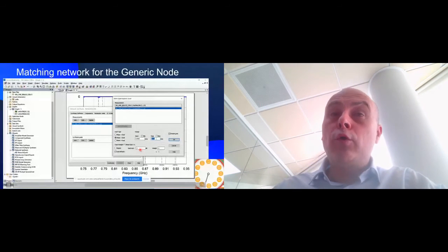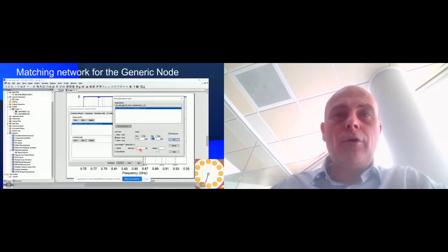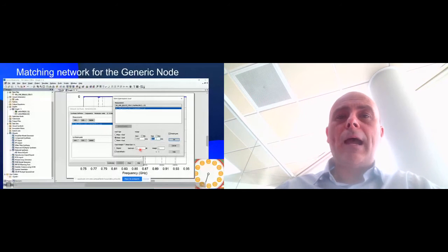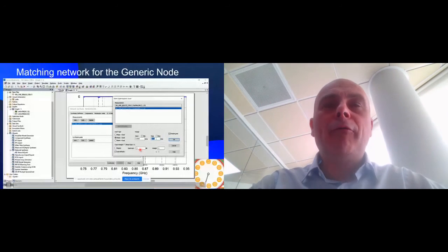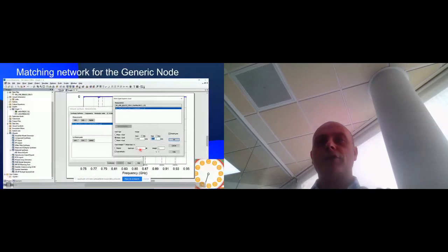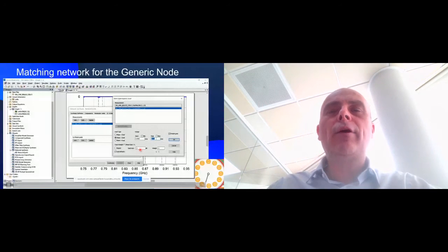In this case, it's only 2 components, and it gives you 2 possibilities. One topology here, another topology, a combination of 2 inductors, for instance. Let's pick up this solution. So we have the antenna booster, and we have the antenna booster with a matching network, and this will represent the transceiver. This port here is the transceiver. It's a combination of a series and a shunt inductance. And let's have a look at the S11 response with the addition of a matching network. In blue, remember, is without matching network, and in pink, we are going to see, wow, it's a great response. An S11 below minus 8, and even close to minus 10 dBs in the LoRa frequency bands.